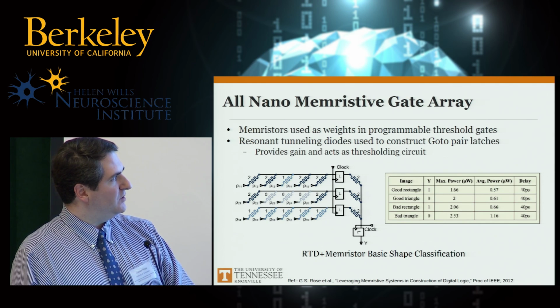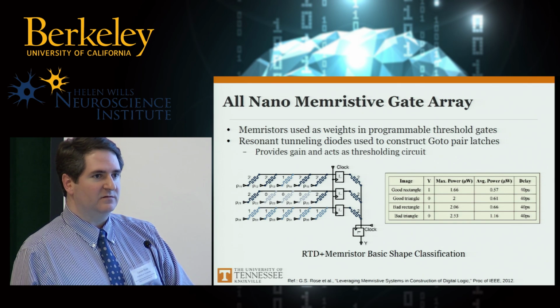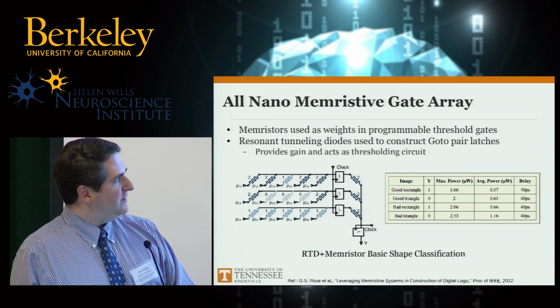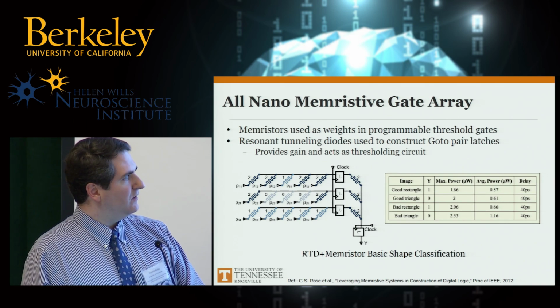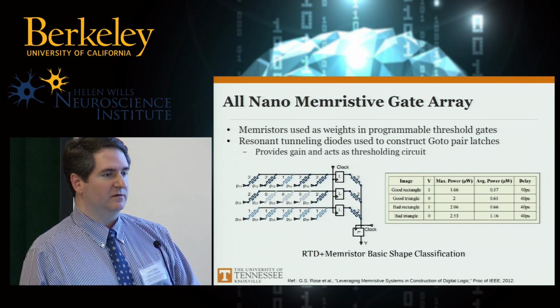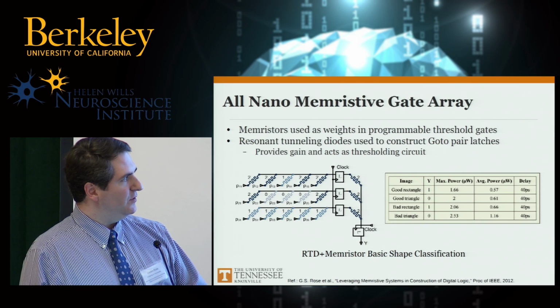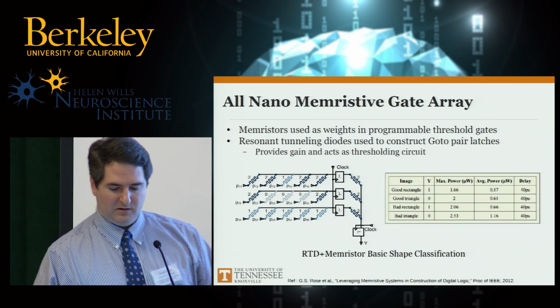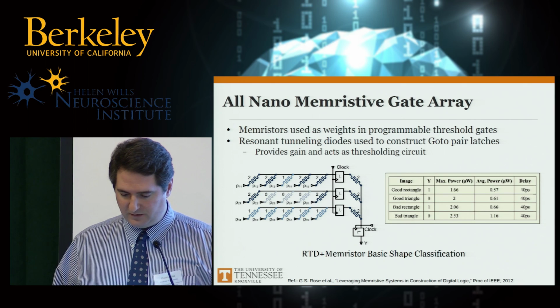It's very simple. But the thing to note is that power is very low. I mean, this is just looking at this nanoscale piece. We're not considering all of the interface circuitry, which of course we would need. But if we just consider all the nano stuff, pretty low. In this case, this was 2012. We were looking at the Hewlett-Packard memristors. That's what we were modeling. For those devices, we got pretty good performance in terms of delay as well. So low power, pretty energy efficient circuits.